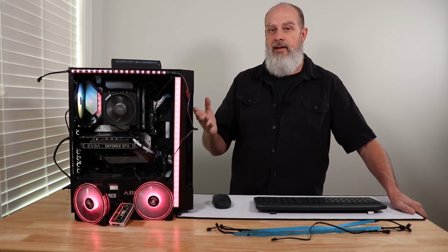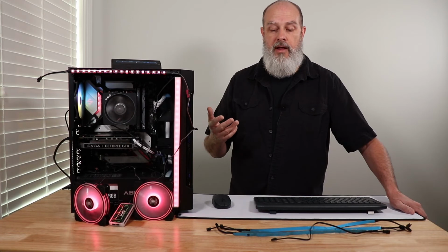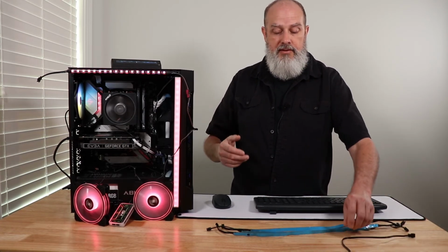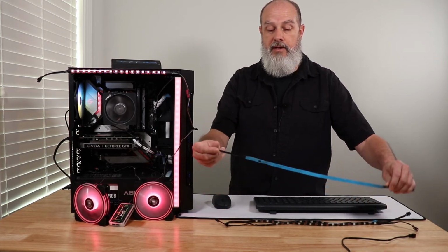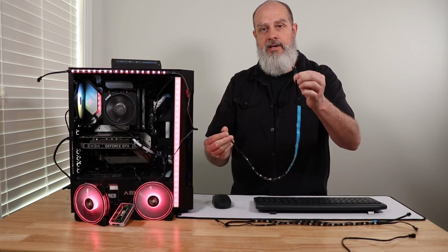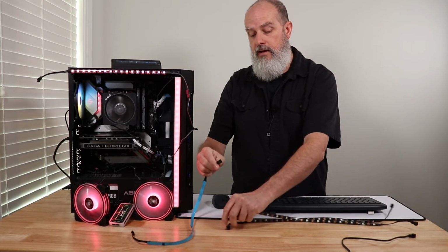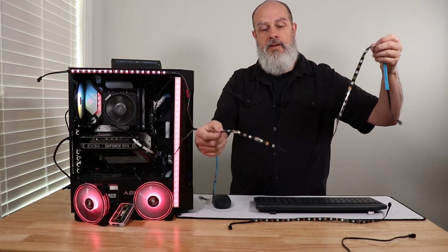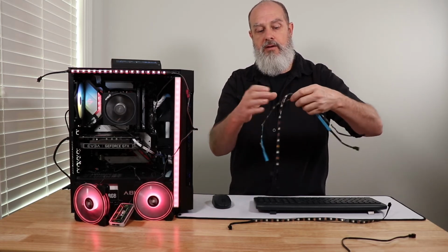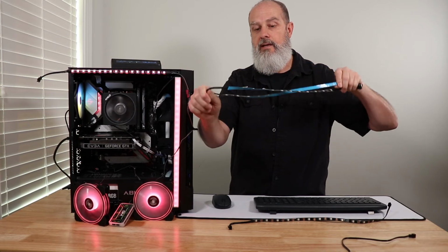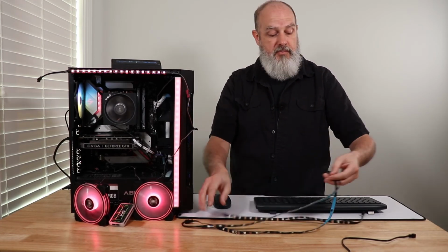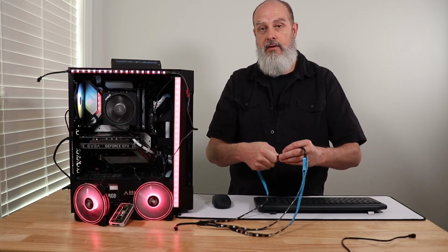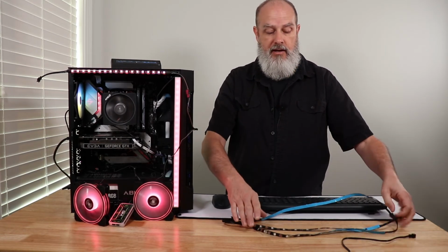Now, if you connect a fan to that, a fan is essentially just a string of lights that are all daisy chained together. Now, the strips, at the end of a strip, so you have your input, and on the end it has another connector where I can easily plug in the next strand of lights. That daisy chains them together, and then I can tell the controller that, okay, you've got 24 LEDs in here now, and so on and so forth. Up to the limitation, you'd want to consult your motherboard manufacturer, because every port's going to have a limitation as to how many LEDs it will address.